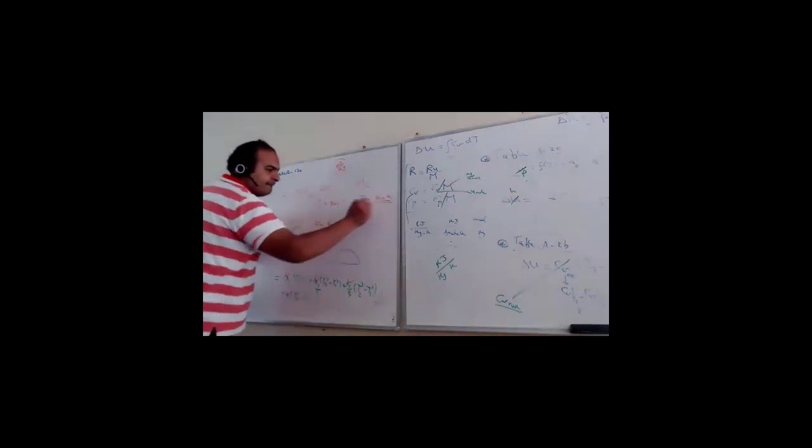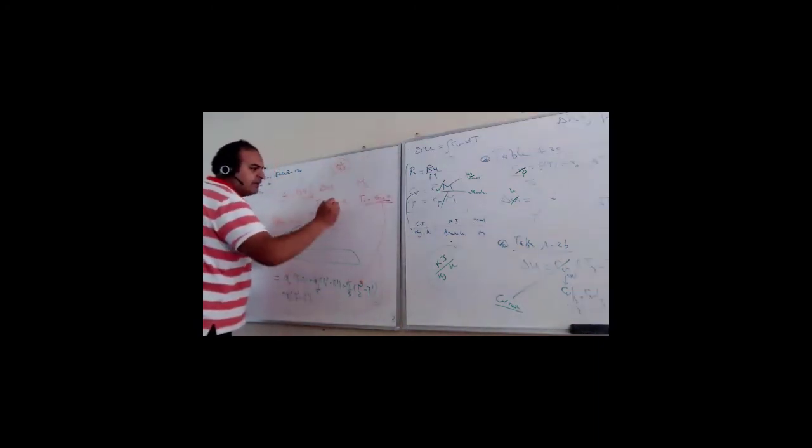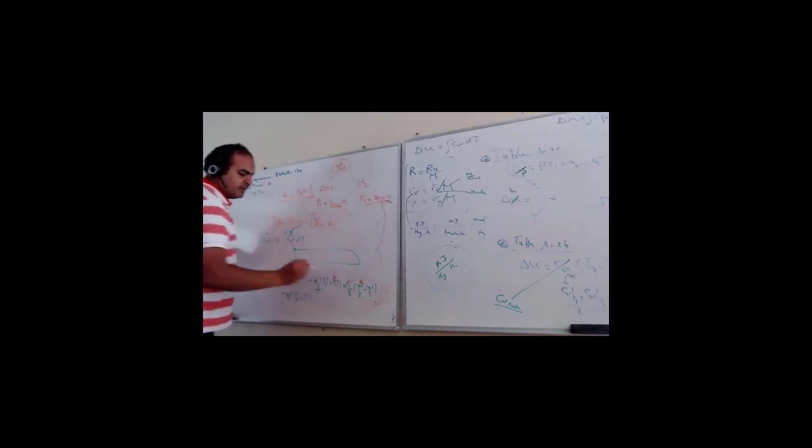These A's are given for the hydrogen. You have temperature T2, any T2. You have any T1, plug in T1 and T2, you get delta U here, kilojoule per kilomole. Just divide by molecular weight. Table A1 has all the molecular weights for all the fluids. Okay, guys? This is the empirical formula, table A to C. If you use average, average is easy.